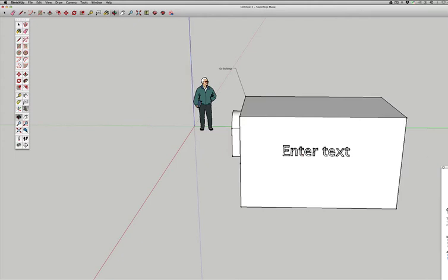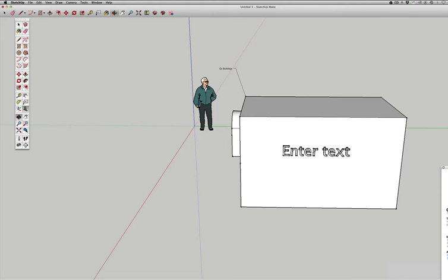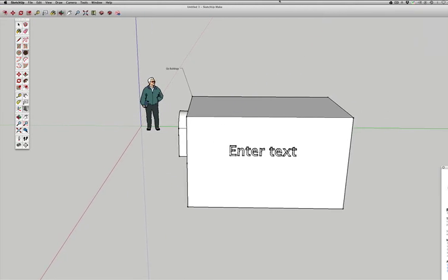How do you change the sides of something? If you go to do that, don't use the circle, go to polygon. I'm going to draw a polygon right down there. Now, when I go to draw the polygon, let me move it up to you. See number of sides? Right there is where I change the sides of the polygon. I'll make mine more like a circle. I'm going to do 18 sides.